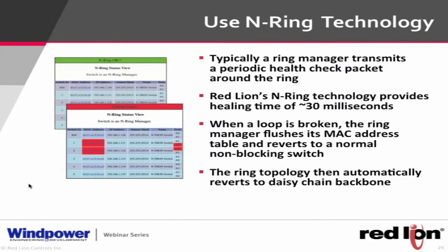So using the in-ring technology, the ring manager sends a health packet around the ring to make sure that it's intact. Once it fails, it does a repeat attempt a couple of times, and then at 30 milliseconds, it will heal, if it's broken.